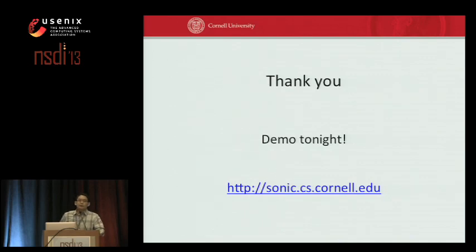The reason that we picked this FPGA board is that the FPGA chip is using a high-speed transceiver which is running at 11 gigabit per second. That's the requirement, because the bitstream is coming at 10.3125 gigabit per second, and we didn't want any physical chips to modify bits. With this chip, it can receive those bitstreams from the optical signals directly, not touching the bits with the high-speed transceiver. That's why we picked that board. So if you want another FPGA board for this functionality, then the FPGA must be using a transceiver that is faster than 10.3125 gigabit per second.